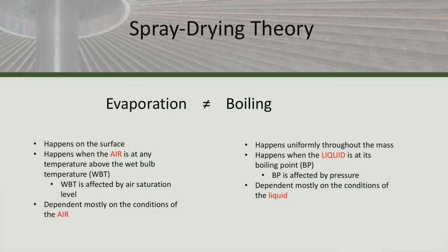And the reason for this is basically that evaporation is not the same thing as boiling, and it's important to understand the difference here. Evaporation is something that happens only on the surface of a liquid, whereas boiling happens uniformly throughout the mass. This is why it's very important for us to create a high surface area.